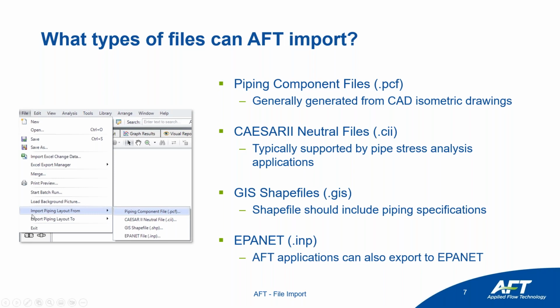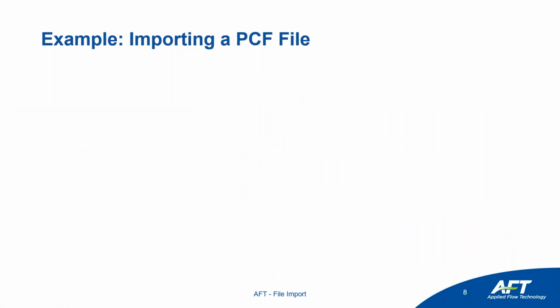So we can import our piping layout from these 4 sources, but we can also export our piping layout out to EPANET, useful if you're trying to review a profile or something like that. So those are the 4 options that we can perform an import on.